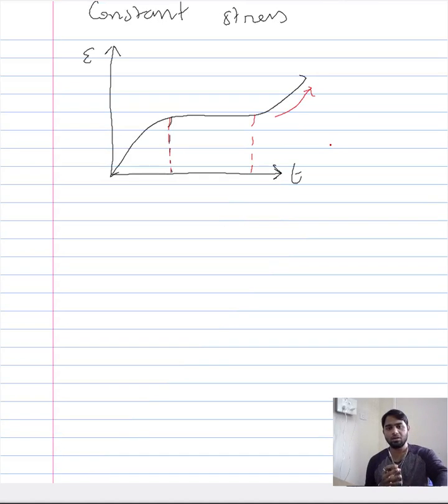Now, let's get back to making some physical sense of this curve. When you talk about creep in relation to the tensile test, in a tensile test you will gradually increase the stress and the strain gradually increases. In contrast, even though we might apply a tensile loading at high temperature in creep, the stress does not gradually increase. That means you are imposing a definite load immediately to the material.